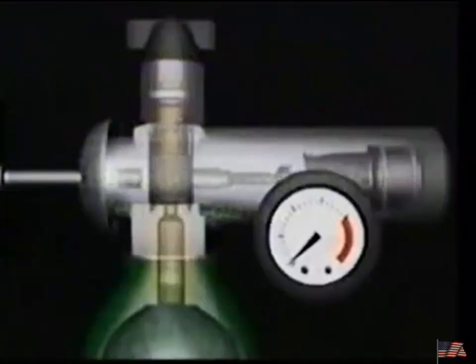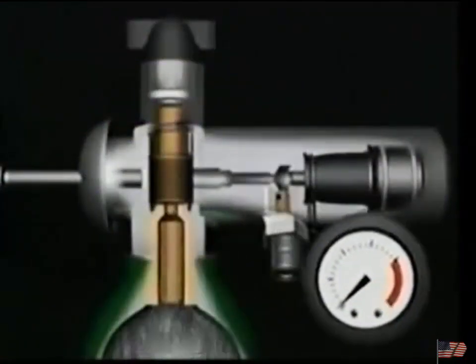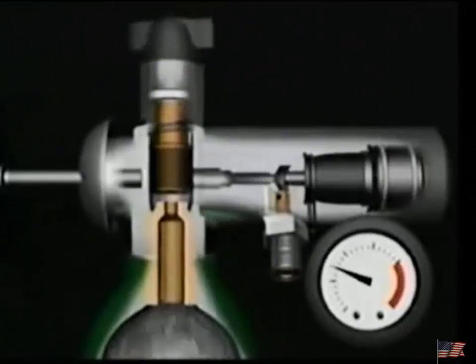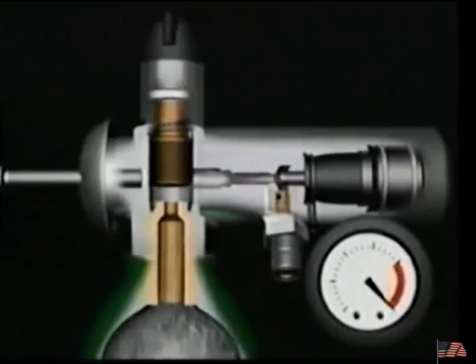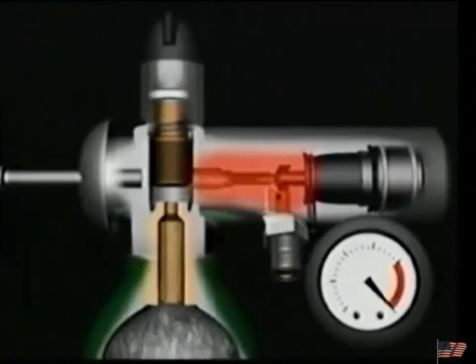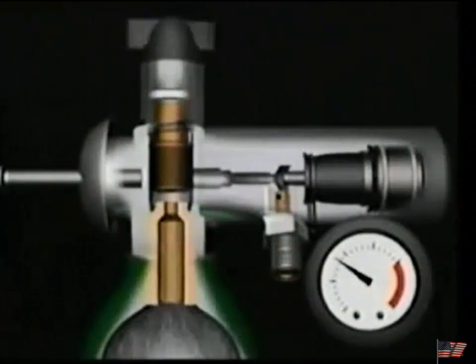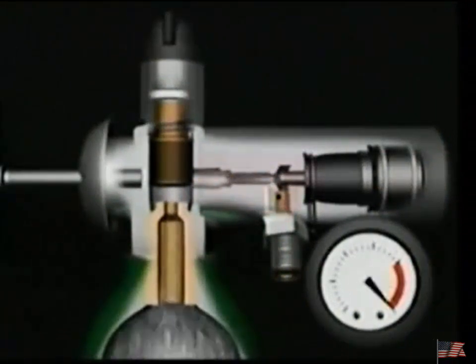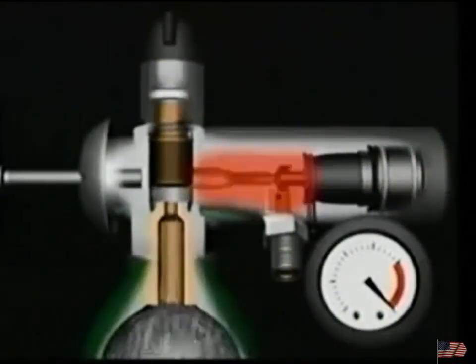Another contributing factor is adiabatic compression, also called the heat of compression. This happens when you open the post valve and pressurize the regulator. Oxygen rushes into the high-pressure side of the regulator. As the gas rapidly compresses in this closed compartment, heat is generated, which can also ignite any non-metallic part of the regulator. That heat can also ignite contaminants inside the regulator, which brings me to my next point,